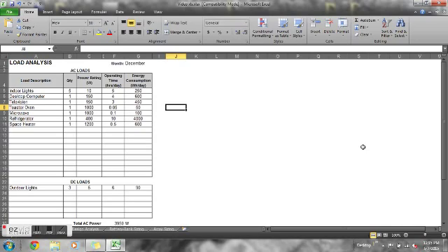And now going back to the first step in sizing a standalone PV system, which is the load analysis. The load requirements determine the size and cost of the PV system, therefore the energy efficiency of your appliances is paramount. For this reason, steps should always be taken to improve the efficiency of your loads. This may involve several factors, including getting more efficient appliances or being more cognizant of your energy use, such as turning off the lights or eliminating phantom loads.